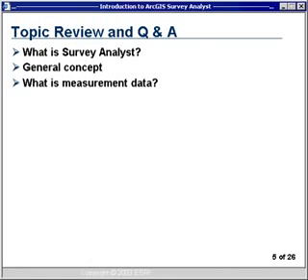Thank you, Christine. I'd like to add one more comment to the question about typing in property descriptions, such as parcel descriptions, into Survey Analyst. When we're editing GIS features within ArcGIS, Survey Analyst maintains the data in a surveys database or a measurement database, and we're actually editing the GIS layer. So you can use your normal tools to enter values for the parcels through the editor. But Survey Analyst will have tools where you can also transfer attributes. And in fact, all the data collectors collect attributes when they make measurements. And so that data will be available.